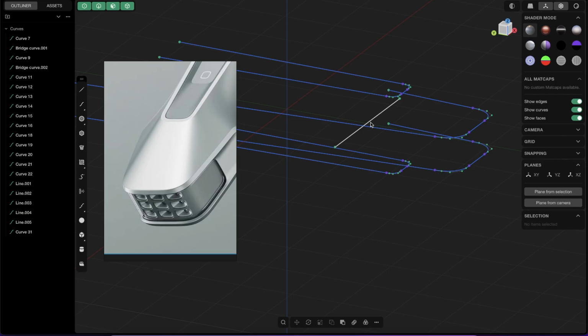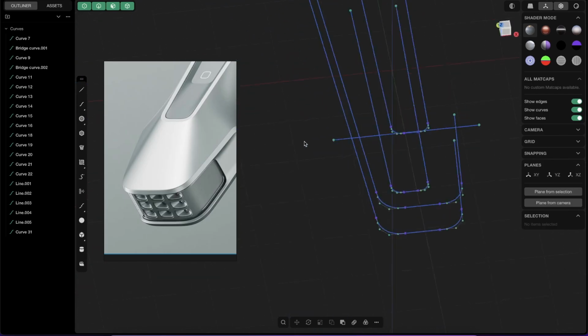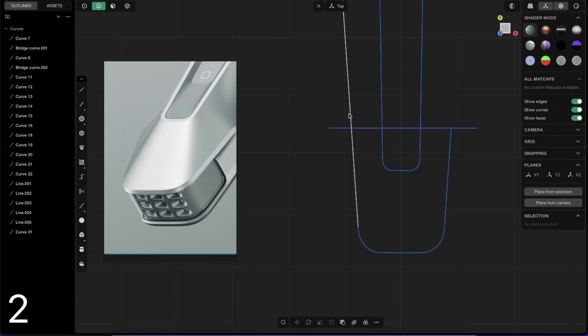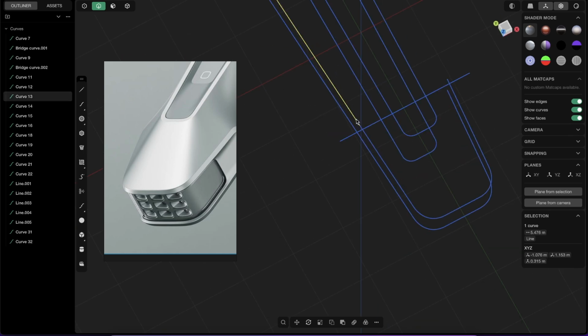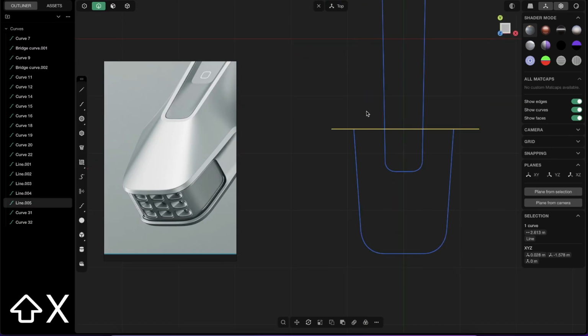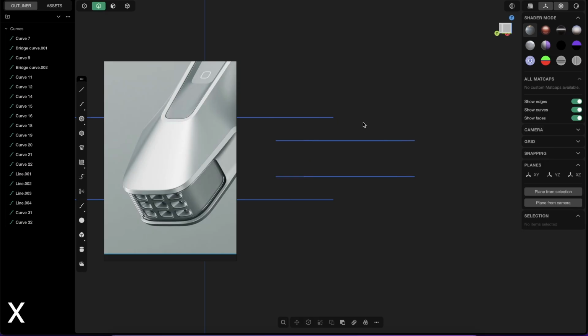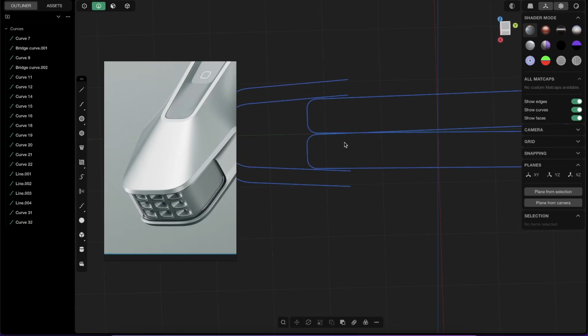And then the second, third time, when you do it with better quality, obviously you know already that you will mirror things over, so you can then save some time. But again, select the curve, Shift C, select the line, right click, delete this, select the long curve, top view, Shift C, cut, bam. So again, Shift C, delete it, perfect. Delete also the line in the middle, and we are back to normal.